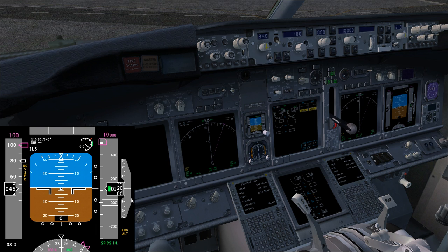We have now a vertical speed tape. This vertical speed tape actually shows the vertical speed of the aircraft. Over or under this scale will actually be seen the actual rate of descent or climb in hundreds of feet. Actually, you will see here, for example, if you're climbing at 1,000 feet per minute, you can see plus 10. Up here we have the scale